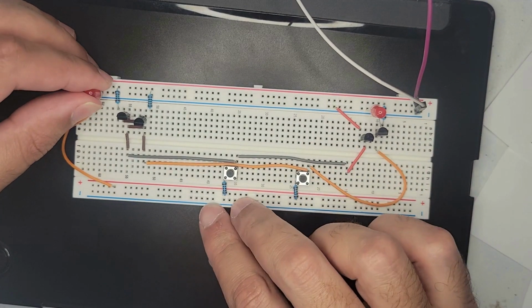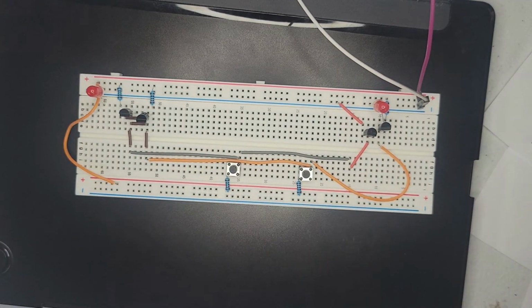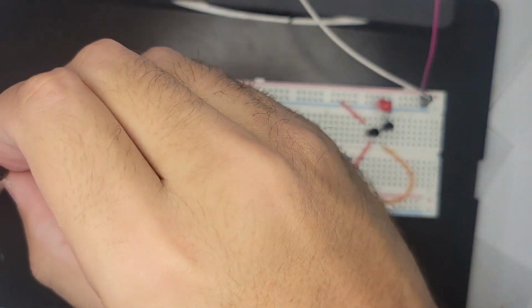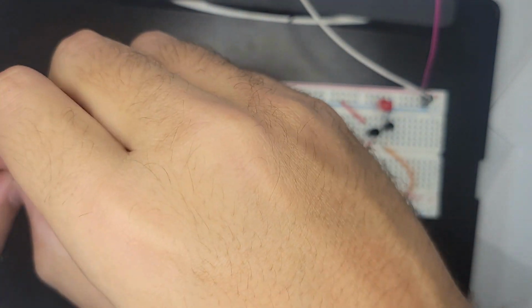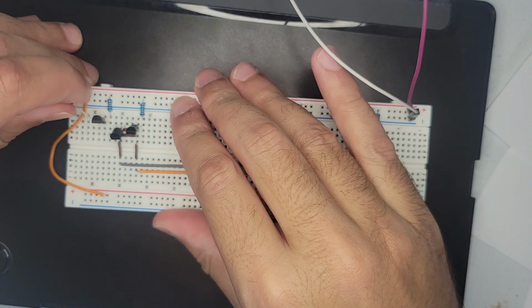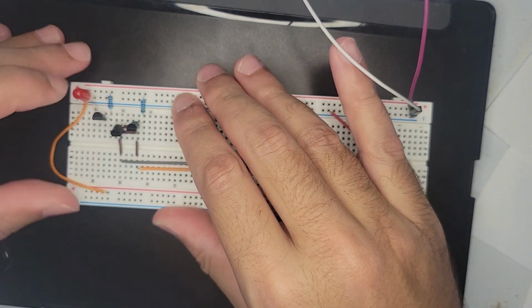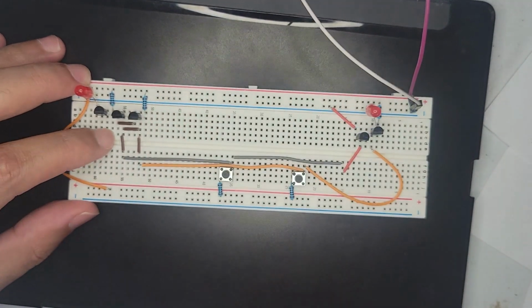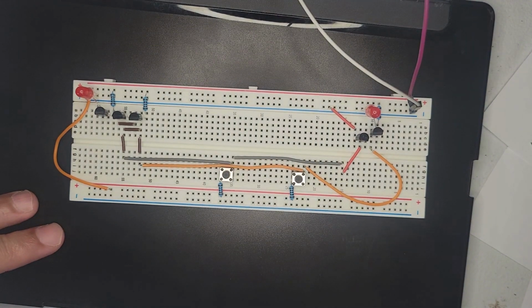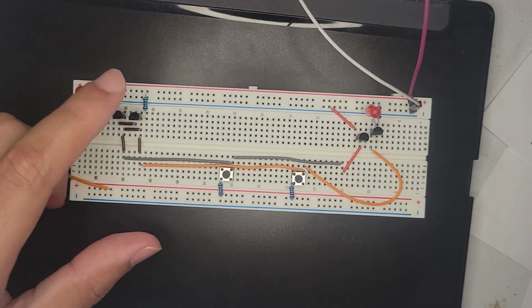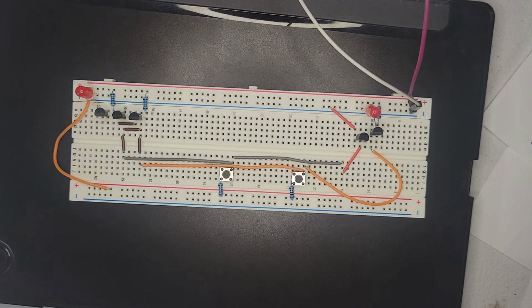And what I'm going to do now is this guy's going to power a transistor whose emitter will go to the LED. Okay, and then it will just take the output from our OR gate into the base. So basically, instead of the OR gate itself powering the LED, it will power another transistor that has like fresh power, we could say.